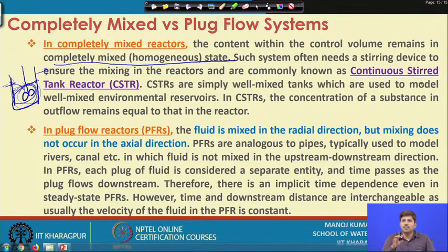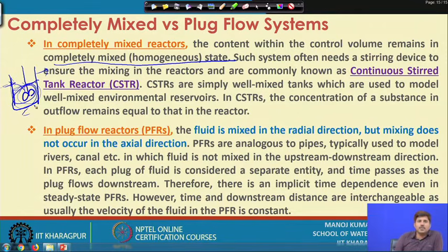So, these CSTRs are simply well mixed tanks, okay. As we discussed, they are in the form of tanks. They are just well mixed tanks, and these are used to model well mixed environmental reservoirs. So, if you have, let us say, a lake or those kinds of things where good enough mixing is there, you can use the CSTR concept for modeling, or in engineering treatment systems we often design this kind of process intentionally. So, in a CSTR the concentration of a substance in the outflow remains equal to that in the reactor. So, that is one of the important aspects of the CSTR.